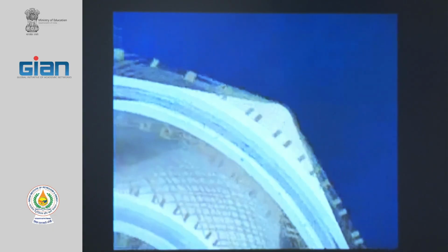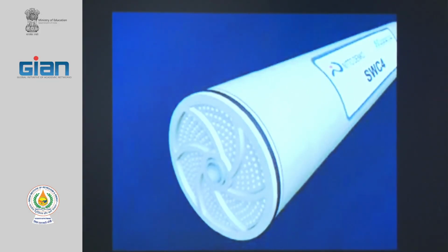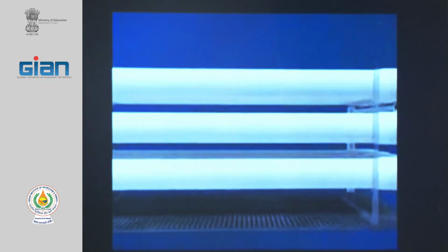Clean water or permeate flows from the feed spacer, through the membrane surface and into the permeate channel, and then in a similar direction to the permeate center tube of the element, and is collected into the core tube.